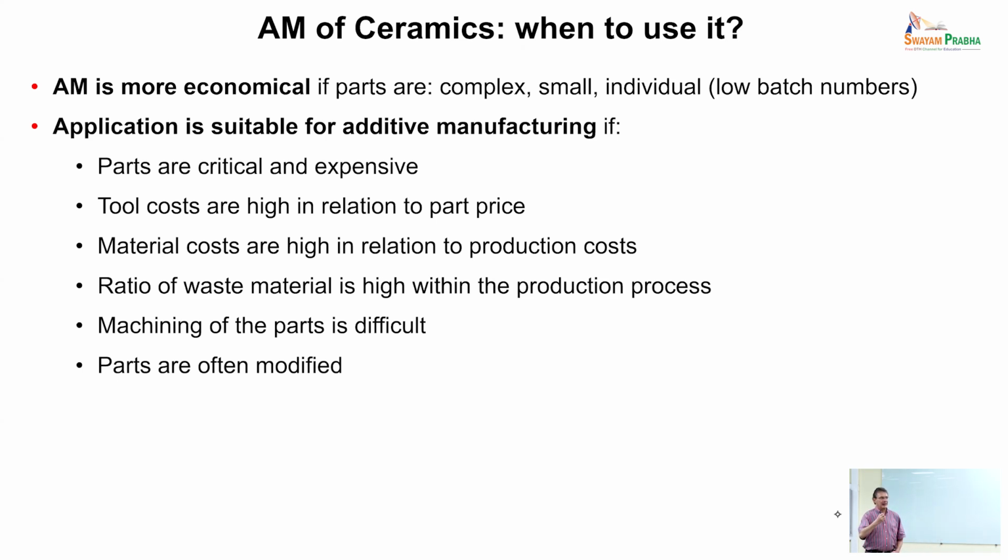And one reason for using additive manufacturing is to use it when it is more economical than conventional manufacturing. And this means that if the parts are complex, if the parts are small, if the parts are highly individualized, if you need to modify the shape of the part, the design of the part frequently, then additive manufacturing is certainly faster, more economical, and better than conventional approaches.